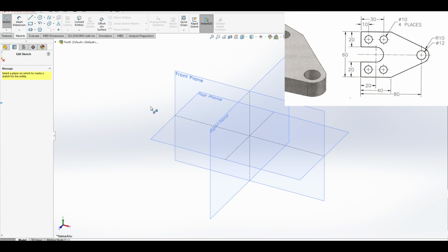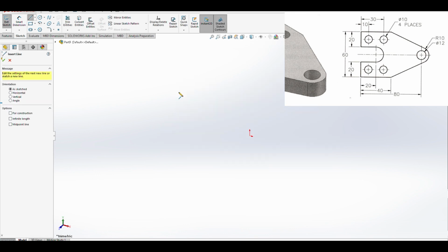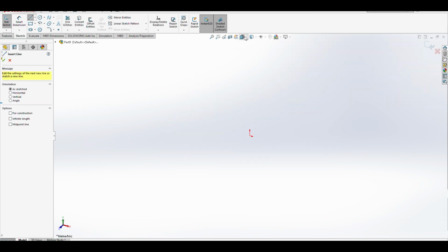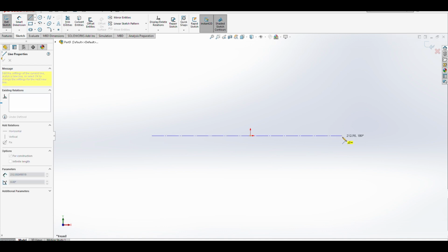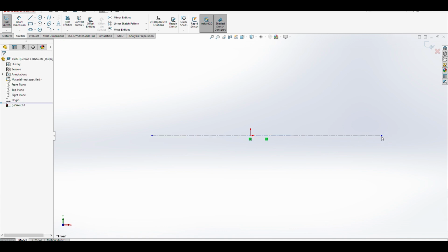Okay, we're getting ready to do sketch number 5 now. We've come down here and we've changed this to millimeter gram second. We're going to click on front plane here. I'm going to go ahead and line this up so everything's straightened out with the origin point, and we are in our front view. Okay, the first thing I want to do, and this one's a little bit of the trickier ones, we're going to lay out a center line because we're going to mirror this part off of that center line.